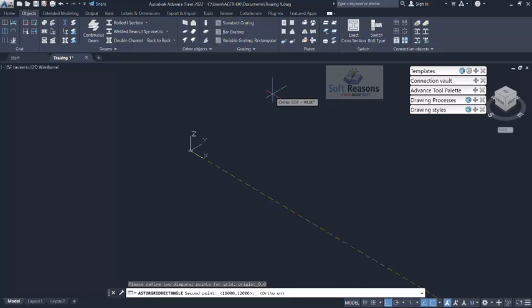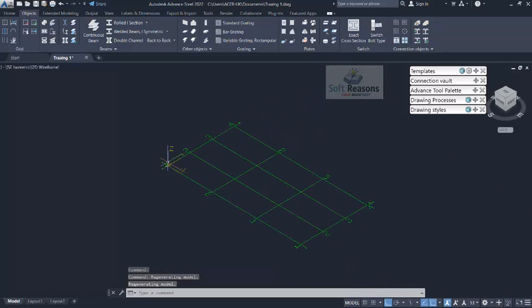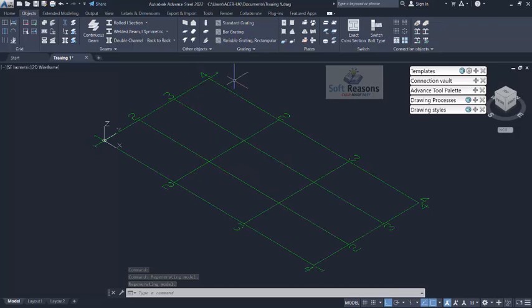You move your hand upward and then key in the width of the structure, which is 10,000 millimeters, and then you enter. So once you enter, you have grid lines. So you can now use the wheel of the mouse to zoom in, zoom out to get to see the whole of the grid lines that you set successfully.